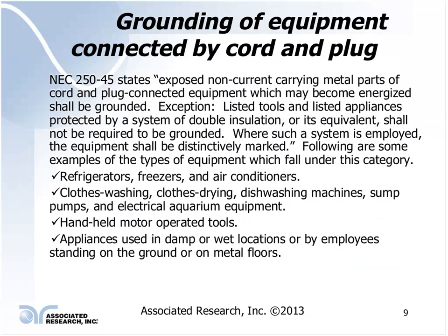It states that any listed tools and listed appliances protected by a system of double insulation or its equivalent shall not be required to be grounded. Okay, if it has this system of double insulation, it is not required to be grounded.